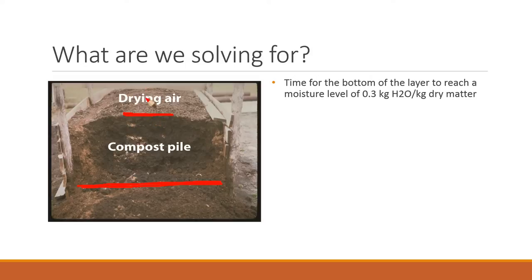That's because it's a convective boundary condition where the moisture content at the surface is not provided, but a convective boundary condition is provided, and the moisture at the surface keeps changing as drying progresses. Another way to look at this is that the mass transfer coefficient at the surface is not infinite, and therefore the surface is not at equilibrium with the surrounding air.